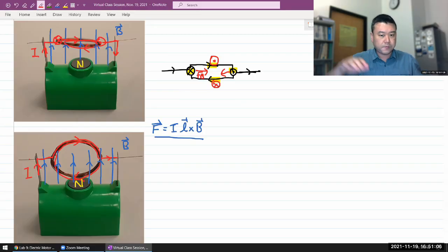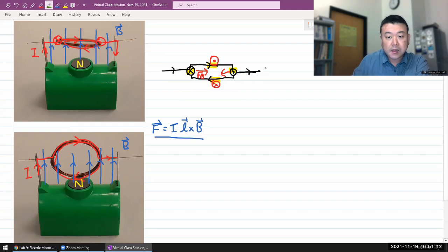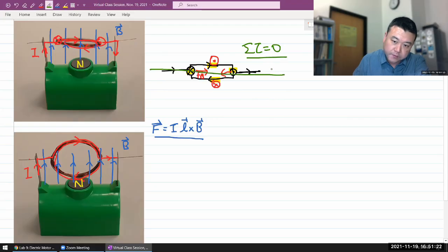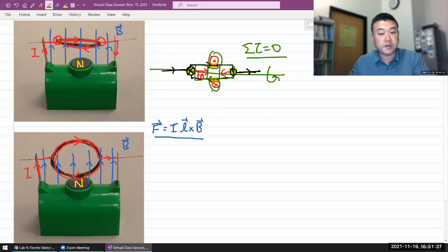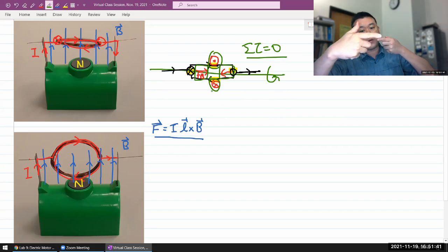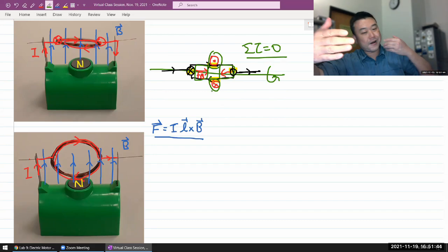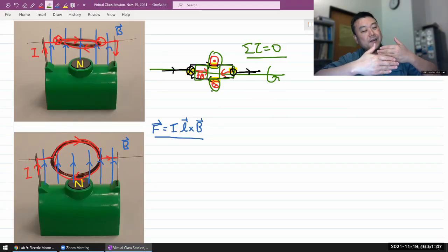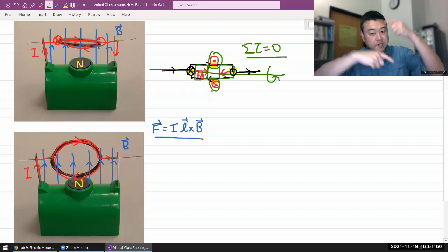And as you look at that horizontally lying loop, if you are figuring it looks like the net torque is 0, then you'll be right. These forces around this center of rotation have no lever arm. These two forces were never going to cause any torque. And these two forces, if this loop is horizontal, then the lever arm for these two forces is 0. They're just compressing the loop in this way, but they are not causing it to rotate.